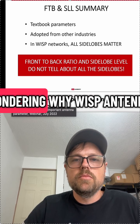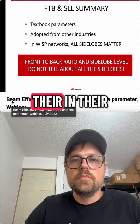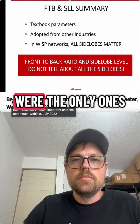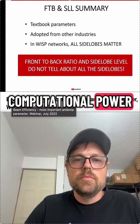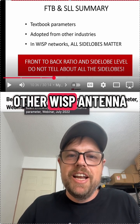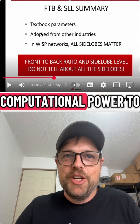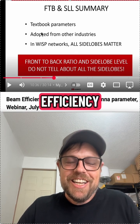And if you're wondering why WISP antenna manufacturers use them and show them in their data sheets, my guess would be it's simply a remnant of the times when these parameters were the only ones that were easy to determine and calculate without enough computational power. So he says the reason why other WISP antenna vendors use the front-to-back ratio and side lobe level is because we don't have enough computational power to determine beam efficiency.